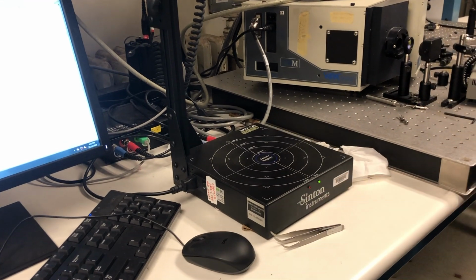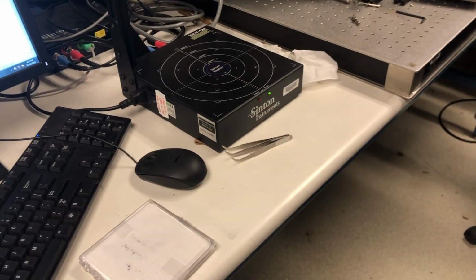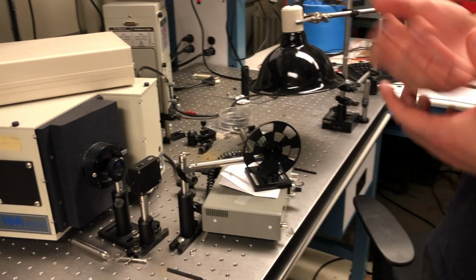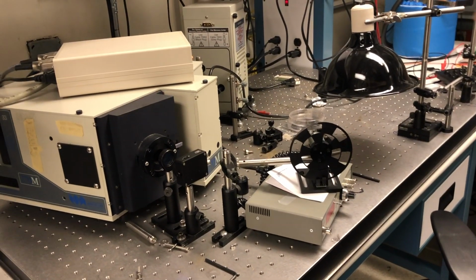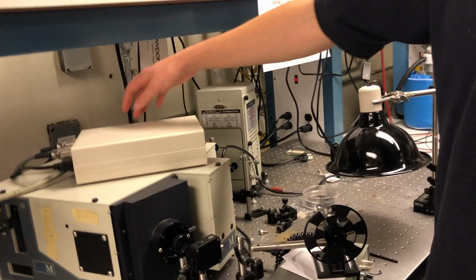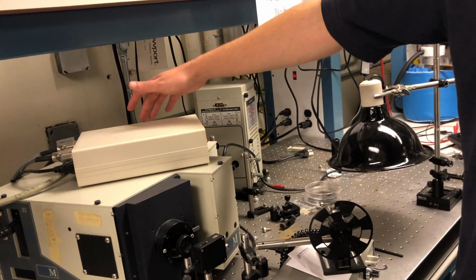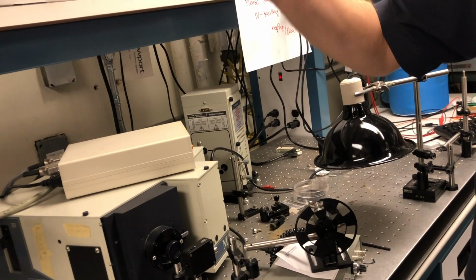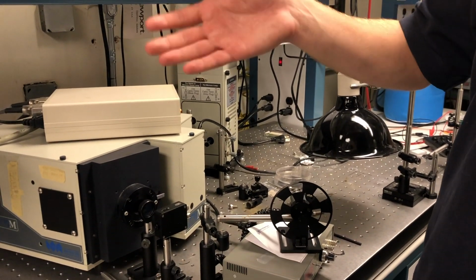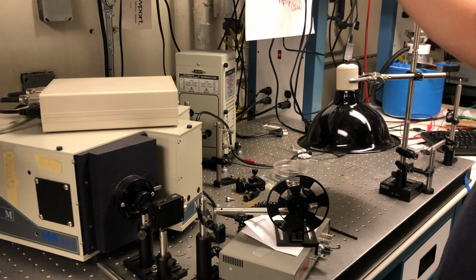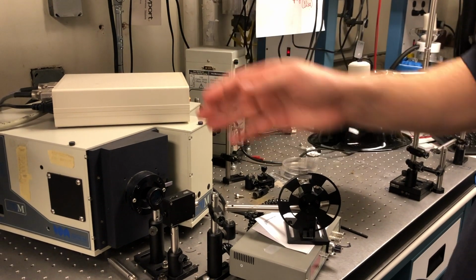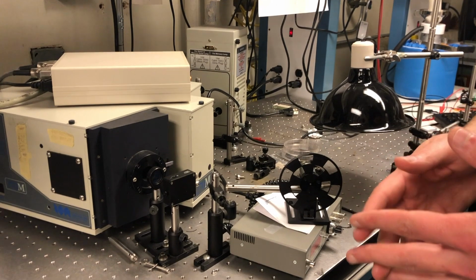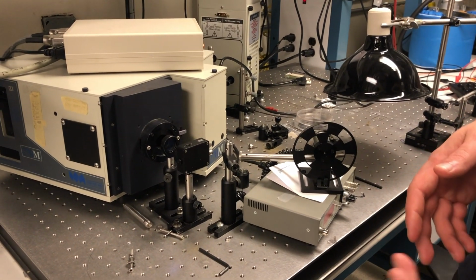So that's that. Last thing we'll talk about really quickly, we also have an EQE setup. This is pretty similar to measuring IV or measuring your solar cell device, but instead the lamp goes into a monochromator. So it'll take the incoming white light and split it up into its components, from blue through red to the infrared. And you can give each one of these select wavelengths to the device at a time and measure the current at that light, or the efficiency, whatever you really want to measure.